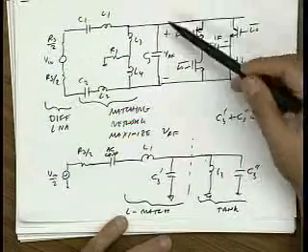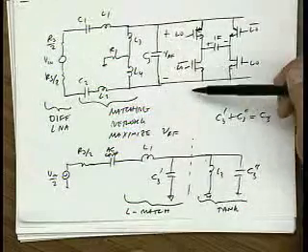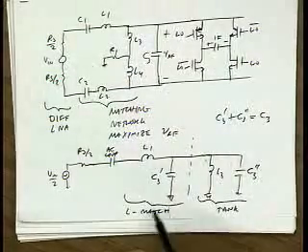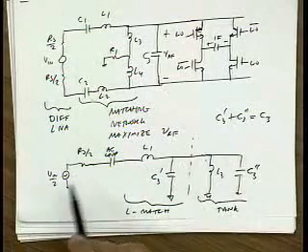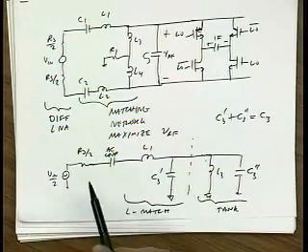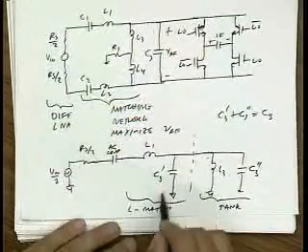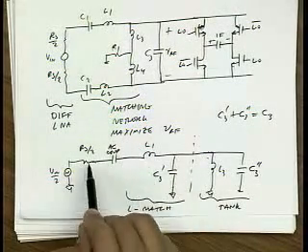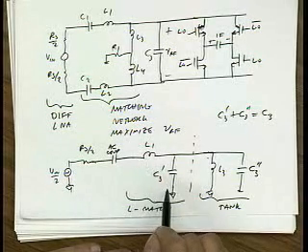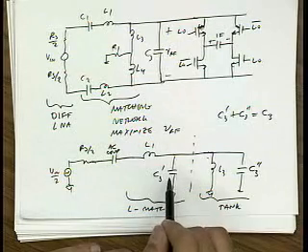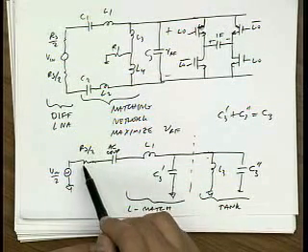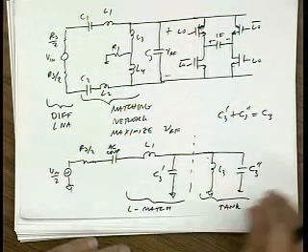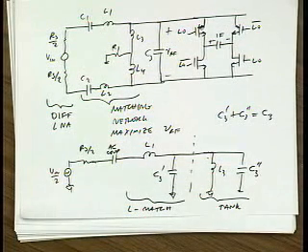So what I'd like to do is resonate out all the capacitance at this node and apply the RF voltage as large as I can over here. And I know that this L matching network can take this voltage and boost it by the quality factor of the matching network. Remember, this is a series resonant circuit. So in resonance, the current in the circuit flows through the source and through the series reactances, and the voltage across these series reactances is Q times bigger than the voltage across here. And since in resonance the voltage across here is all applied across here, we get a Q boost in the voltage. Right? Okay. Any questions about that?